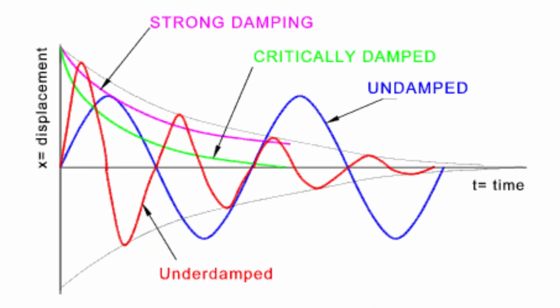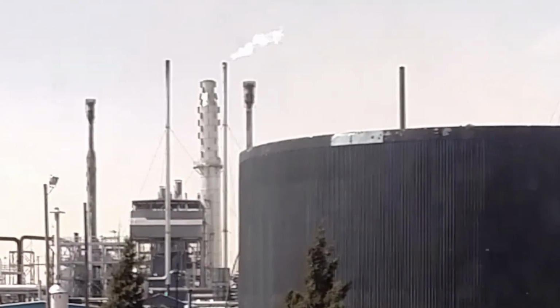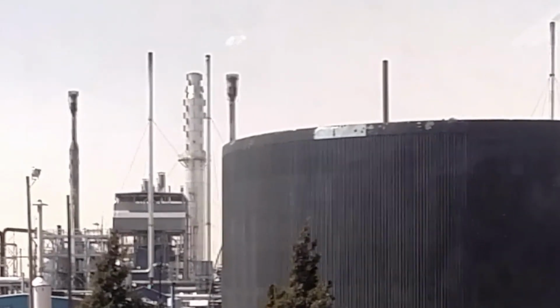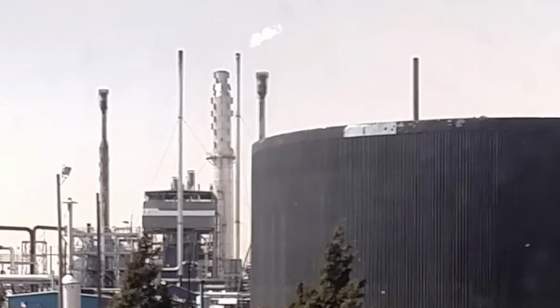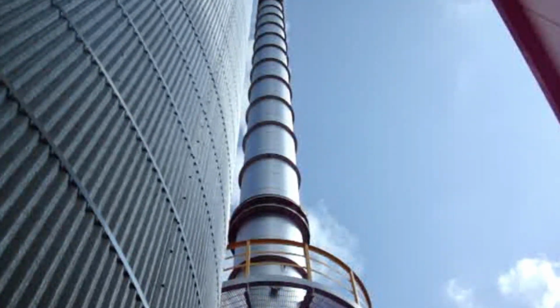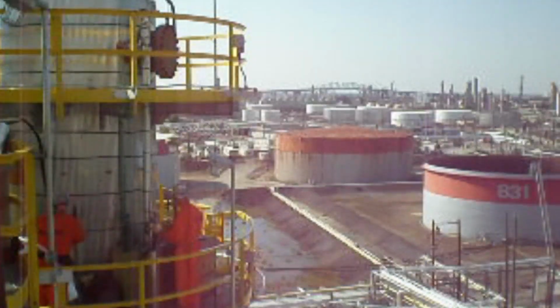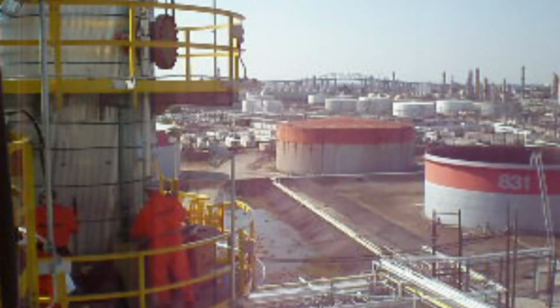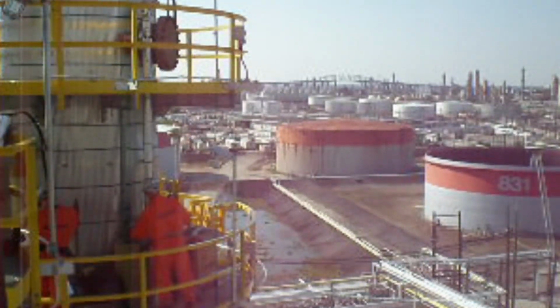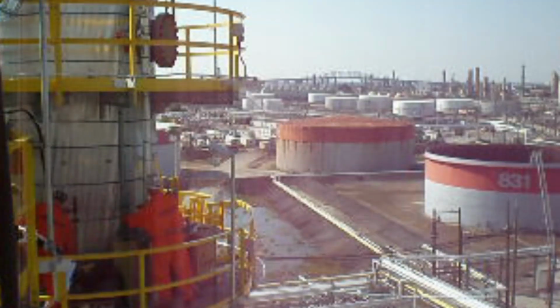Every structure has a certain amount of inherent structural damping that will help diminish the effects of harmonic vibration on a structure. The structural damping has the biggest effect on the structure's sensitivity to vortex shedding. There are many factors which contribute to the structural damping, such as the type of connections, materials being used, soil, foundation, etc. We don't often know all of these details when designing the structure, and even if these details are known, the only way to really accurately determine the structural damping is to erect the structure and perform testing. This is obviously not practical or economically feasible in nearly all situations.